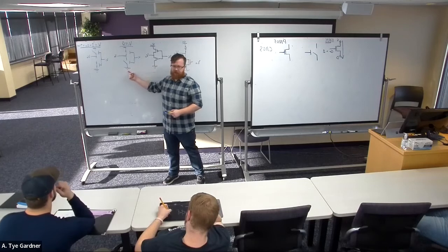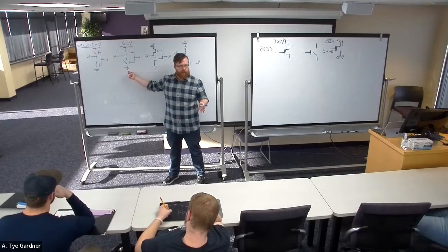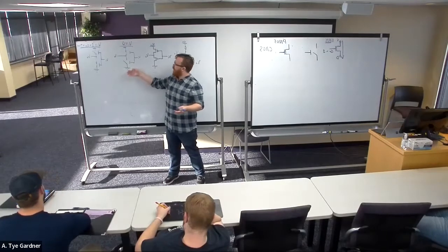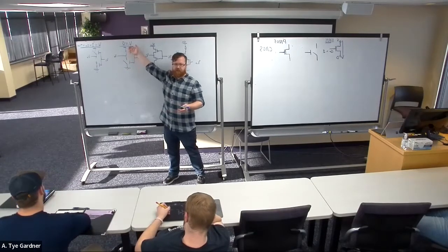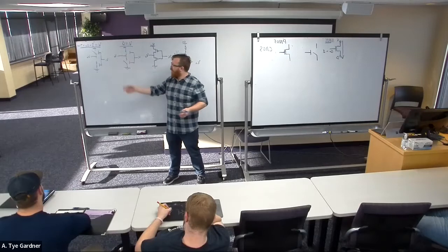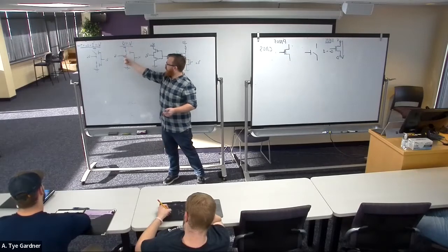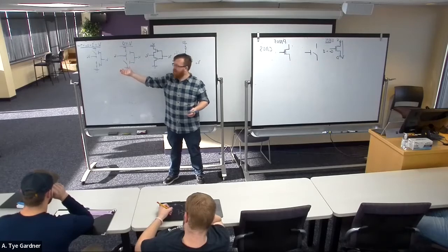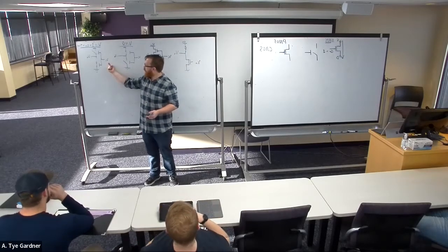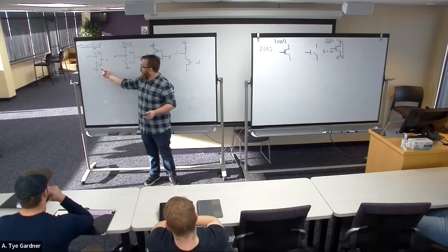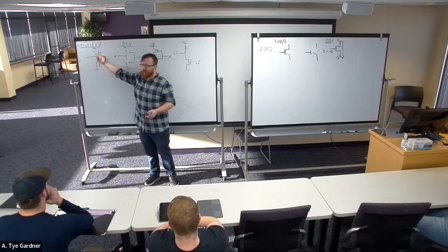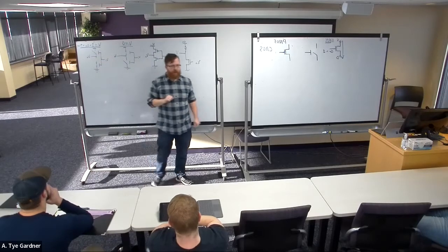In this case, we're not connected to ground, right? The switch is open, it can't see ground, therefore not ground. But we are connected directly to VCC, or on. So the input VN is 0 and the output VO is 1. This is an inverter, right? Because if VN is 1, then that closes the NMOS, connecting it to 0, and then opens up the PMOS. We build an inverter.